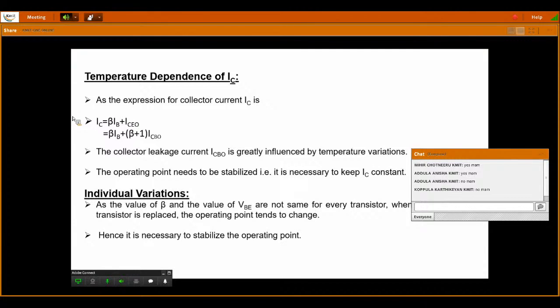For example, a 1 kilo ohm resistor with plus 5% will be 1005 ohms in some cases. The same resistor with a tolerance of minus 5% would be 995 ohms. So the amount of current flowing through the biasing resistors R1 and R2 may vary.